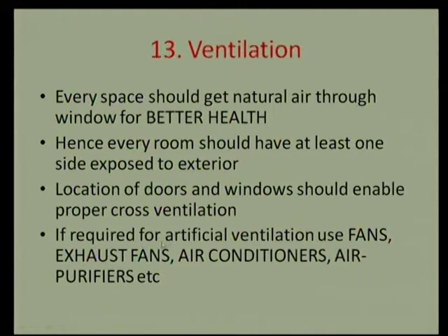Artificial ventilation is required if the proper location of doors and proper planning is not there, or sometimes it is not possible to do the planning because the situation may be very congested, the land may be in a very densely populated area. Like in Ahmedabad, a building located in a very densely populated area, like Kalupur or Lift Road area, you cannot provide openings in all the rooms. So in that case you have to plan for artificial ventilation using fans, exhaust fans, air conditioners or air purifiers.